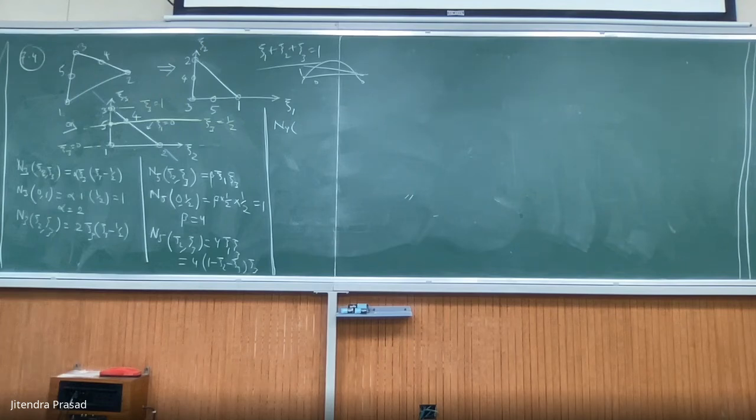So we only have to see N1 and N2 satisfy the linearity. That's what it means, basically, I think. Again, this is the way it's written. It looks like you have to enforce it for all shape functions like that, but it's not possible. There it is 0, you cannot do it.